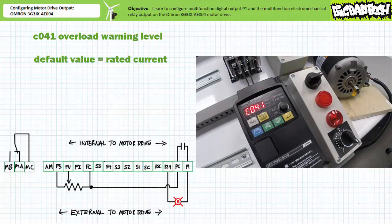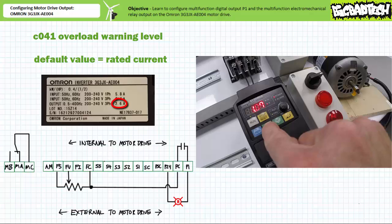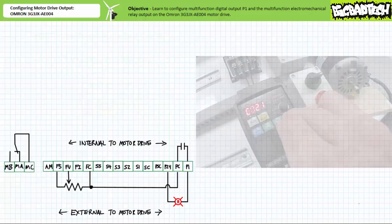Navigate to communication parameter C041, overload warning level. The default warning level is the rated output of this drive, in this case 2.6 amps, as indicated on the label affixed to the side of the drive. Decrement this value to, let's say, 1.1 amps, and press enter to save it.